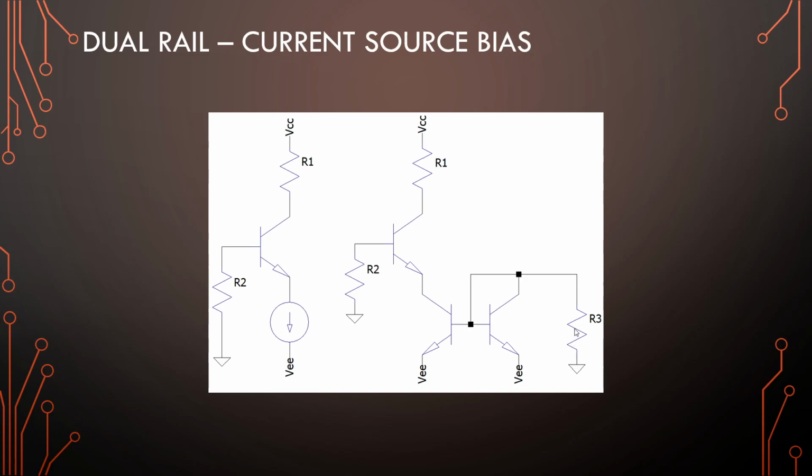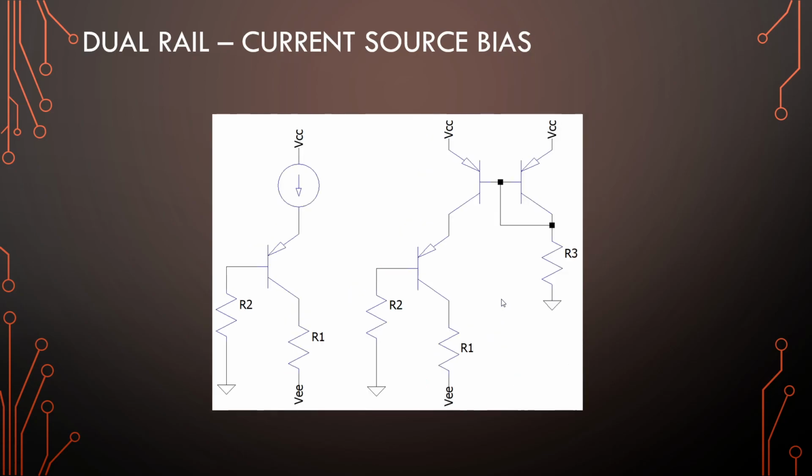Then this resistor value here will just be a little bit larger to accommodate a larger voltage drop across it. So you can bias a transistor, have a correct VCE value, right, half, be able to adjust the input impedance with 3 transistors and 3 resistors. This is the absolute best way to build an amplifier or bias a transistor. Building an amplifier with this is really easy. So yeah, the PNP version, emitter resistor replaced with current source, PNP devices up top, and you are done.